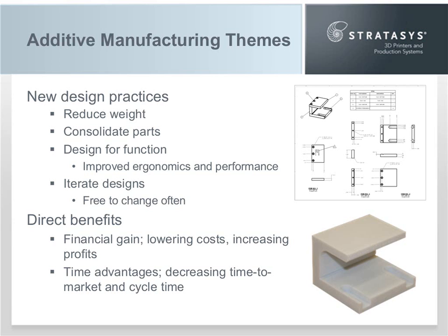Based on incorporating the additive manufacturing process into your tool designing toolbox, if you will, you can actually create whole new design practices. Because of the way additive manufacturing works, we can really do a lot of things to improve tool design. Because we don't have to worry about some of those design for manufacturability rules, you can improve the design by consolidating parts together. No longer do you have to make multiple components and assemble them just to do it cost effectively. We can design them all into one, produce them at one time.